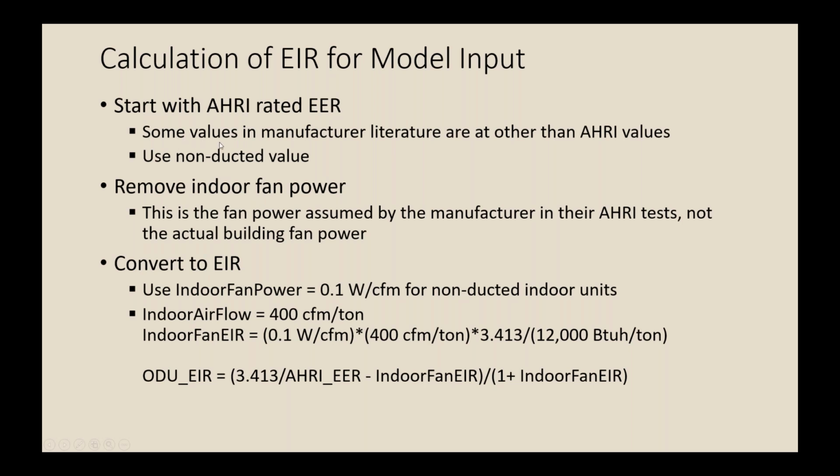As I've been working with these systems, I've found that some manufacturer literature will have values that are listed at conditions other than AHRI. They'll often have both available if you look hard enough, but what you find first might not be what you're looking for. So you have to make sure that it's specified as being rated at AHRI.